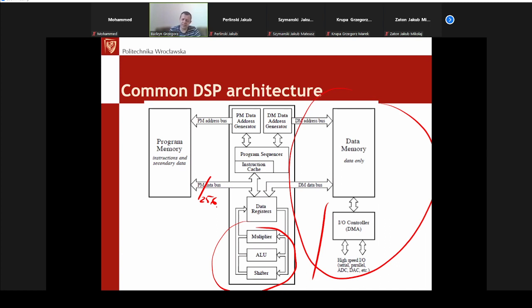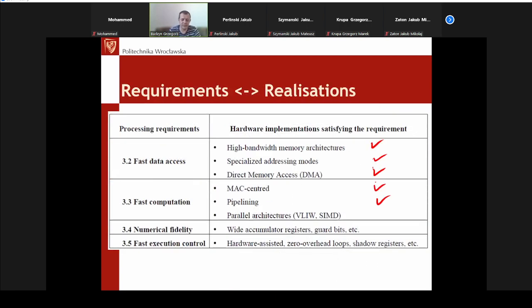In case of the SIMD idea, this is about using a single instruction from program memory working on a batch of data coming from the data memory. They are the mechanism for increasing in general the computation used in a signal processing unit.